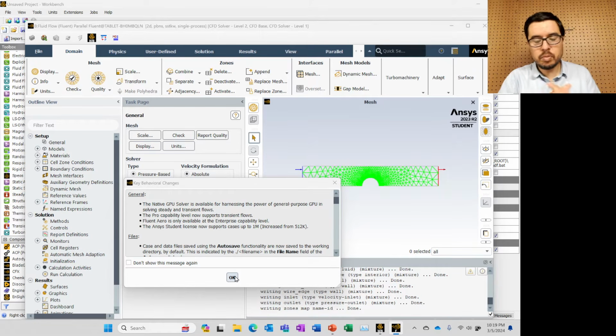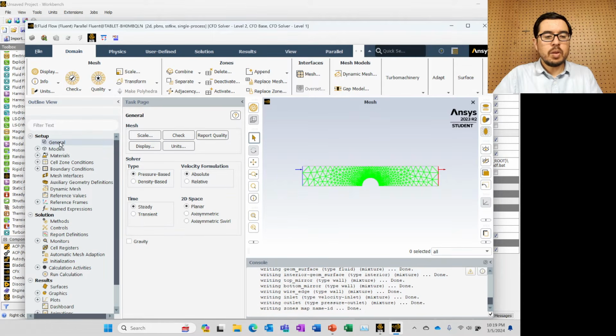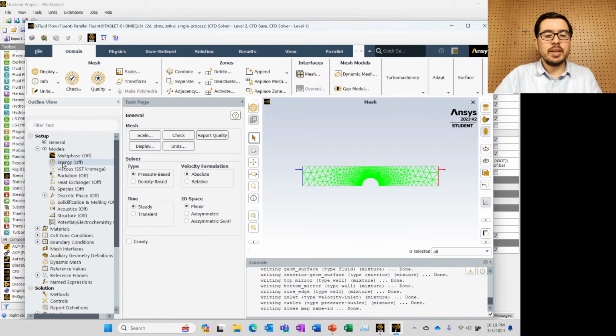And heat transfer, or the heat equation, doesn't have velocity necessarily in it, right? So we have coupled physics here. With the coupled physics, we have an opportunity to turn on the energy. That energy is what allows us to simulate both changes in temperature along with the fluid flow. We're going to be running initially in steady state and planar.